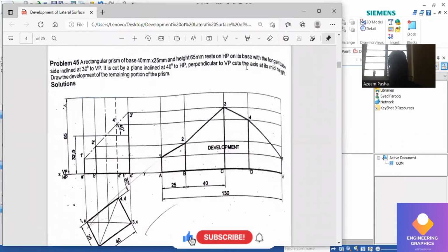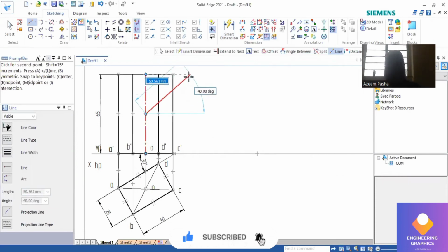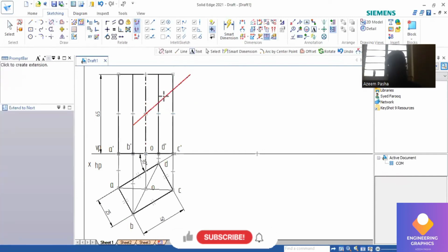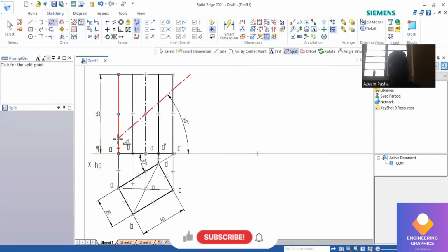Now exactly at the midpoint, we have to draw an angle line for 40 degrees. The midpoint is showing in the axis line. From there I'll give the angle 40 degrees, enter, then extend. Using the extend to next command, I'm going to extend downward also. We can show the angle using angle between here. The upper part of it I'll be showing with a thin line.